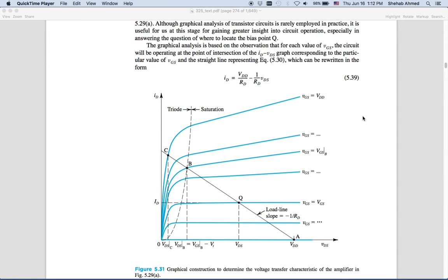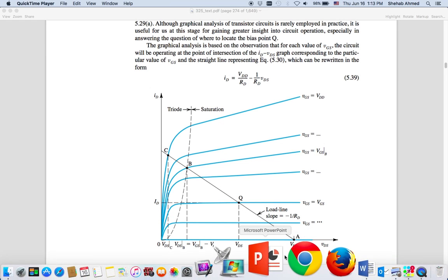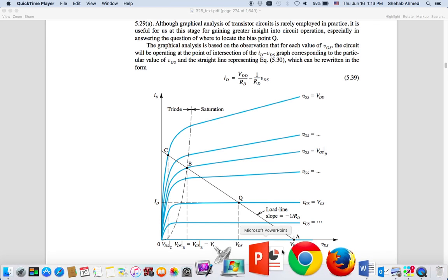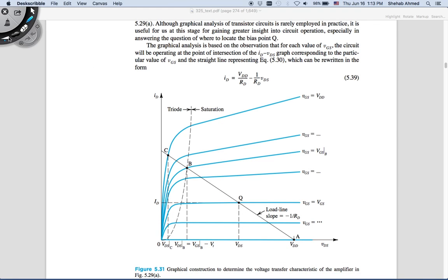Okay, so at the end of the last class, we were talking about DC bias point and amplifier operation. We were able to combine both a small signal and a large signal source at the input gate of the MOSFET, and see how the MOSFET can be operated as an amplifier for the small signal. And we saw what the limit is on the small signal, and that was related to where you placed your operating point, which, in this case, is plotted on the ID versus VDS plot here.